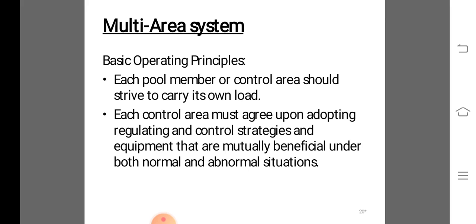Then interconnected operation. Power systems are interconnected for economy and continuity of power supply. For the interconnected operation, incremental efficiencies, fuel cost, water availability, generation limits, tie line capacities, spinning reserve allocation and area commitments are important considerations in preparing the load dispatch schedule.